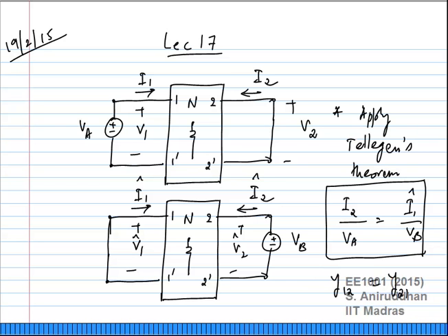So the basic idea was, reciprocity basically relates the excitation for a linear 2-port made of resistors, as what we saw in class. If you excite one port and look at the response at the second port, and you get a certain response, and if you look at the reverse, if you excite the second port and look at the response of the first port, those two are related in some way, right? Depending on what you excite with and what response you see, you can get different forms of reciprocity, and these will be expressed in different ways using the several 2-port parameters that we have studied.